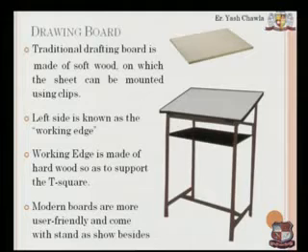How do we define a horizontal drawing? Well, a horizontal line is a horizontal line. Well, if I draw an inclined line and then I turn my face and see, it becomes a what? It becomes a horizontal line. So I need a reference to draw a horizontal line. So I use this edge as a reference and use my T-square for marking what is horizontal for this particular sheet.